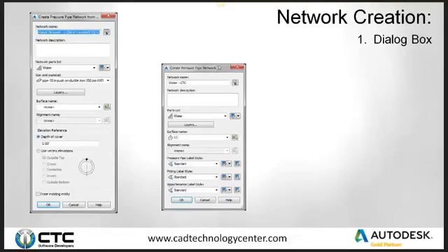The most common one is you're just going to say create a pressure pipe network, and then you're going to build it from scratch. From there, you still get name, parts list, target surface, and then what labels you want it to have. So anytime I create a pipe, it has this label. Anytime I create a fitting, it has this label. Anytime I create an appurtenance, it has this label. Simple enough. 2 different dialog boxes, a couple different options depending on what you pick.